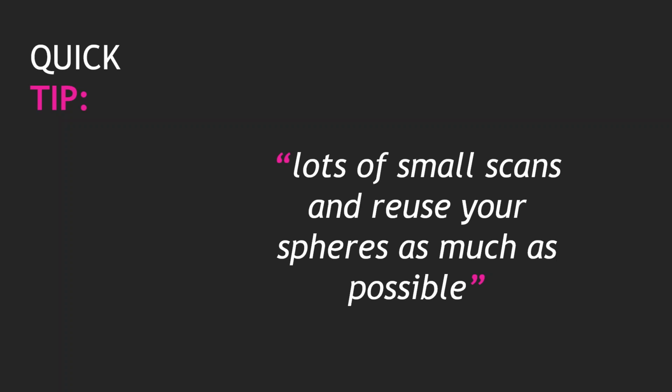Just keep moving it and do as many scans as you can, because this small pipework, which can go down to 1/2 inch plastic or something, can just easily be hidden behind a smaller pipe, a bigger pipe, for instance. So I definitely recommend, if you're scanning a site like that, just keep moving that scanner into lots of different positions and get as many scans as you can. Don't worry about racking up those scan settings, so you're using longer scans. Just use the small ones if you can, that is.